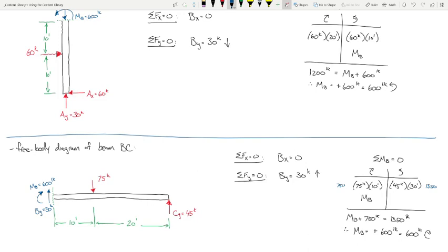Let's consider that what's going on here on this whiteboard is the joint equilibrium. What would happen if I superimpose these forces on top of one another? I've got 30 up, 30 down. What do they sum to? I've got 600 clockwise, 600 counterclockwise. What do they sum to? 0, right? This is what I meant when I said ensuring that you have joint equilibrium.